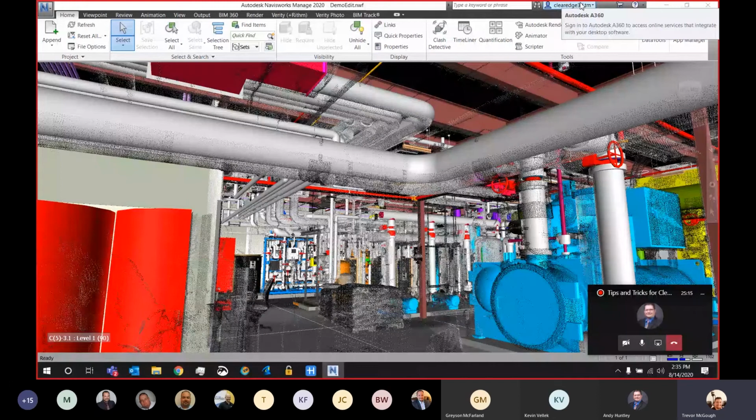The second thing is the point cloud itself. With the point cloud, one of the big tips that I give is having control. Especially using the GTL, that's a great workflow because you can get a point cloud on control. The reason I want to stress that is because how well that point cloud is aligned to the coordinate system that the model is in directly affects the accuracy of the Verity result. By using that GTL robotic total station combo, you can probably get one of the best alignments between the point cloud and the coordinate system.